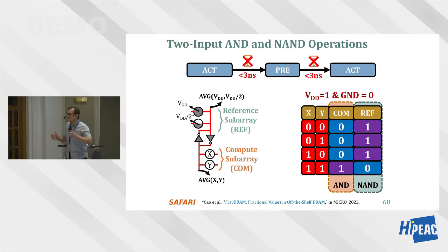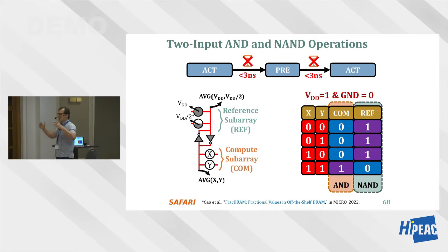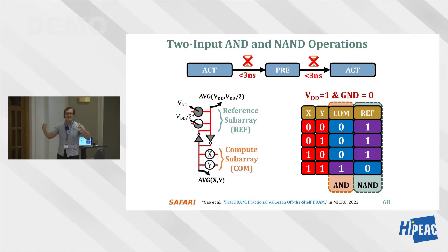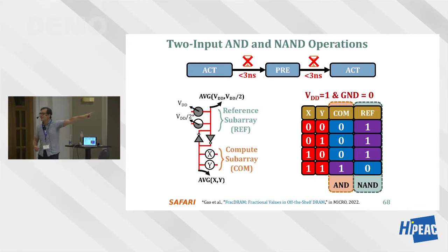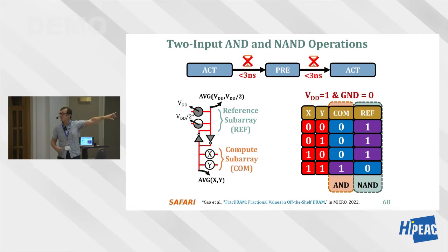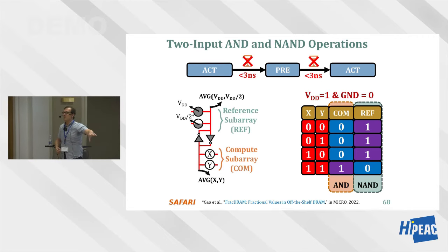So this sounds interesting, right? Yeah, I went to a little bit lower level than maybe some of you are comfortable with, but this is how an analog circuit really operates. And it's not just an analog circuit. That's the beauty of DRAM. There's a sense amplifier, which is an analog to digital converter. So this is not pure analog computation. This is really analog computation immediately translated into digital.